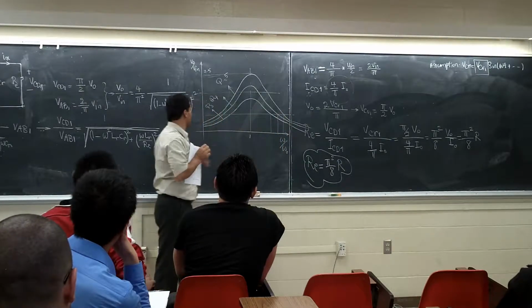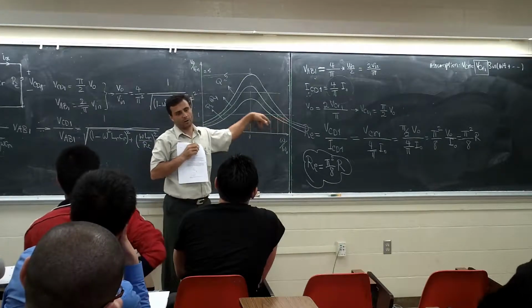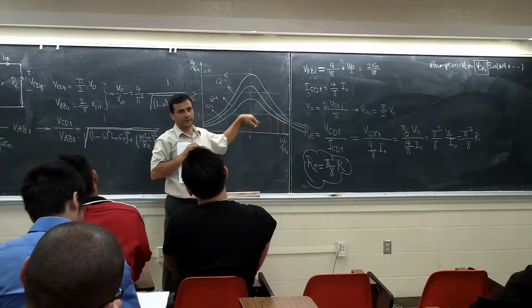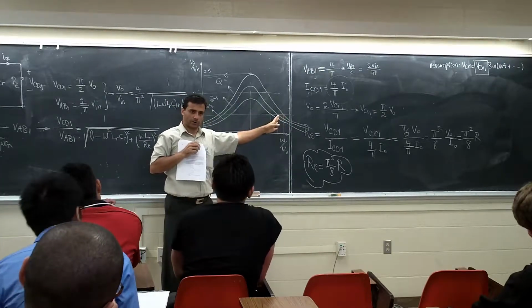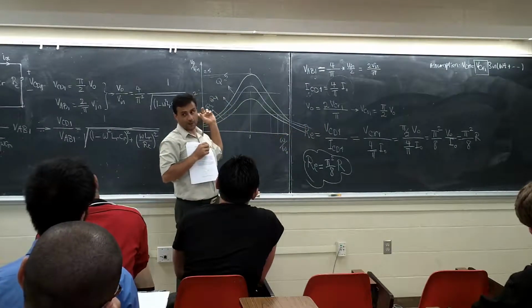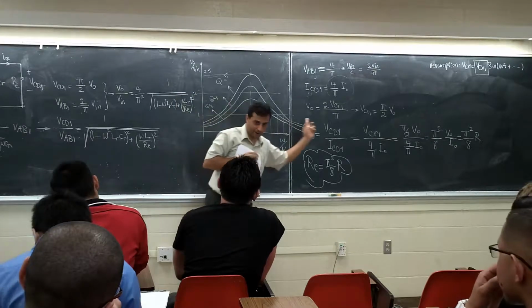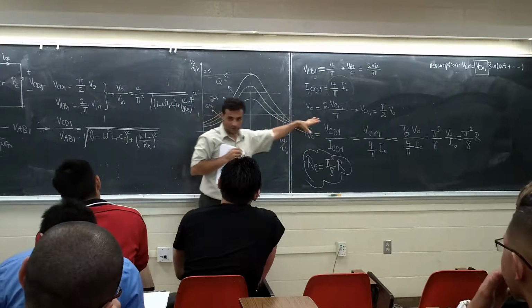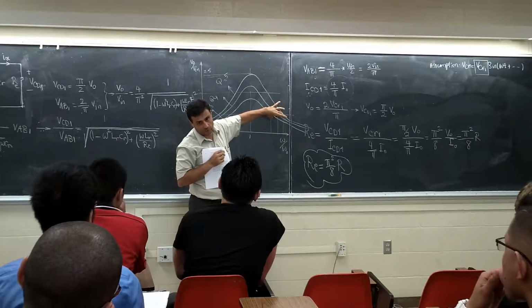So basically, I'm going to get, for example, a ratio of 1, right? So my VO is all the time going to be equal to VE, or I don't know, 0.5 of that one, right? So basically, you should make sure, this is a design. I'll show you in the Infineon problem we're doing. You should make sure this line is going to cut all these things, and your switch can change this much switching frequency.